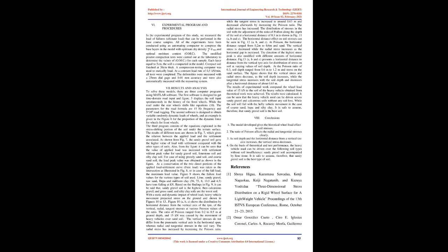An artificial road input time history, x0(t), of the road profile can be generated from the spectral density function, PSDF, of a given road by using digital processing involving the inverse discrete Fourier transform, Ruff 11, Robson 12 and Sieben and Newland 13.